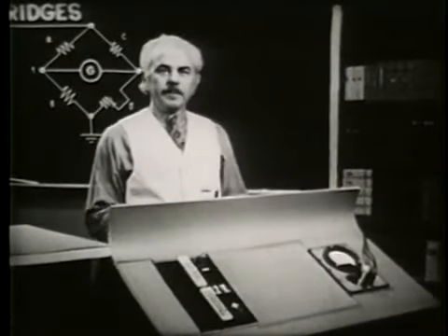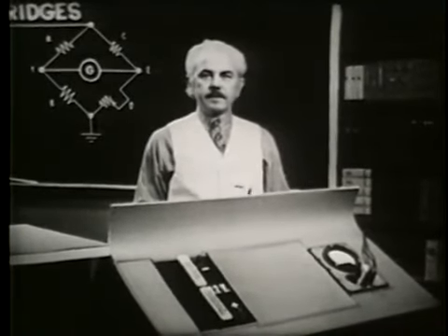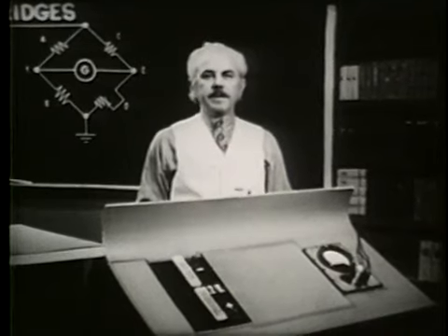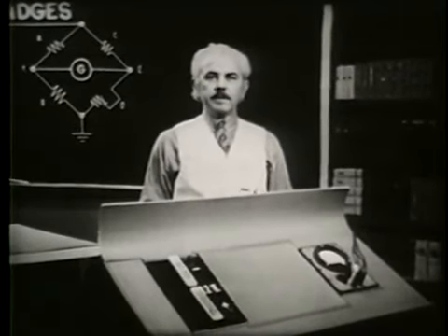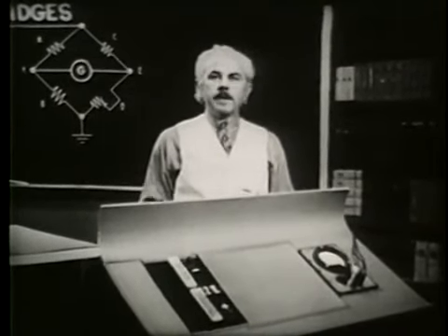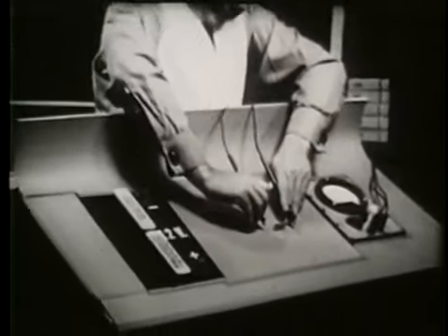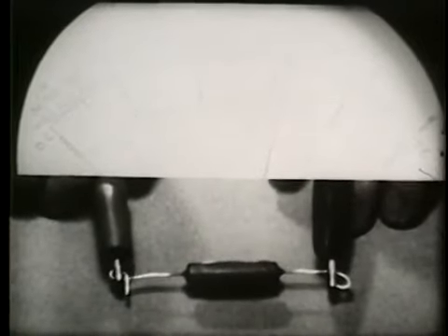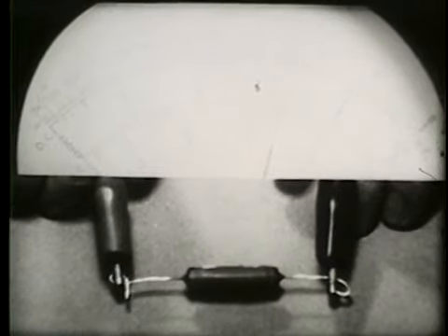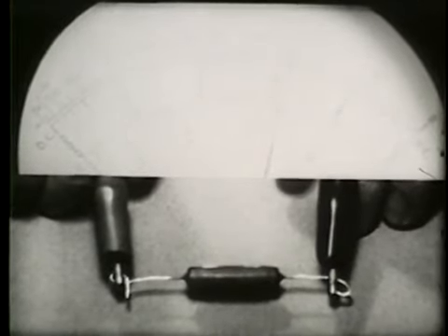In most circuits, the components have a wide tolerance, so there's no need of measuring exact values of current, voltage, and resistance. For instance, when we are measuring this 15,000 ohm resistor, we'll be satisfied with any reading between 12,000 and 18,000 ohms. This one measures 14,000, and that is very good.